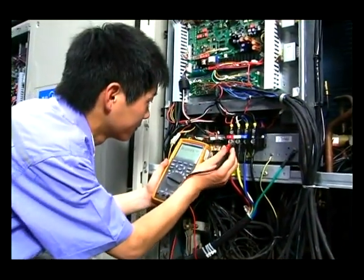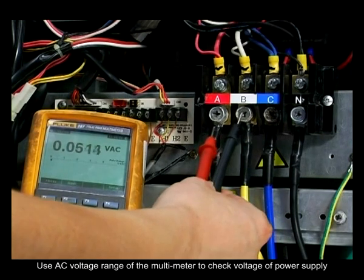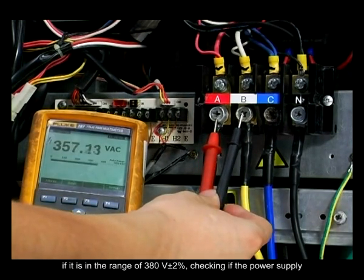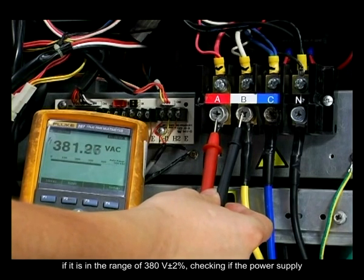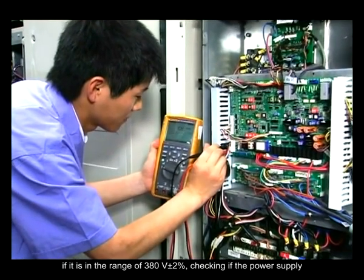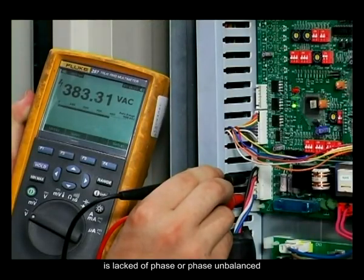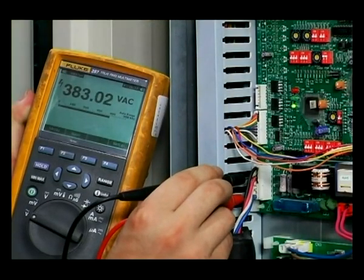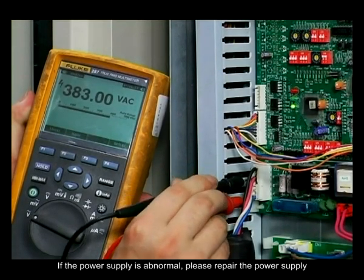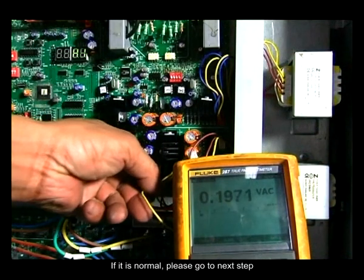Step 1. Use the AC voltage range of the multimeter to check if the voltage of the power supply is in the range of 380 volts plus or minus 2%. Check if the power supply is lacking a phase or phase unbalanced. If the power supply is abnormal, please repair the power supply. If it is normal, please go to the next step.